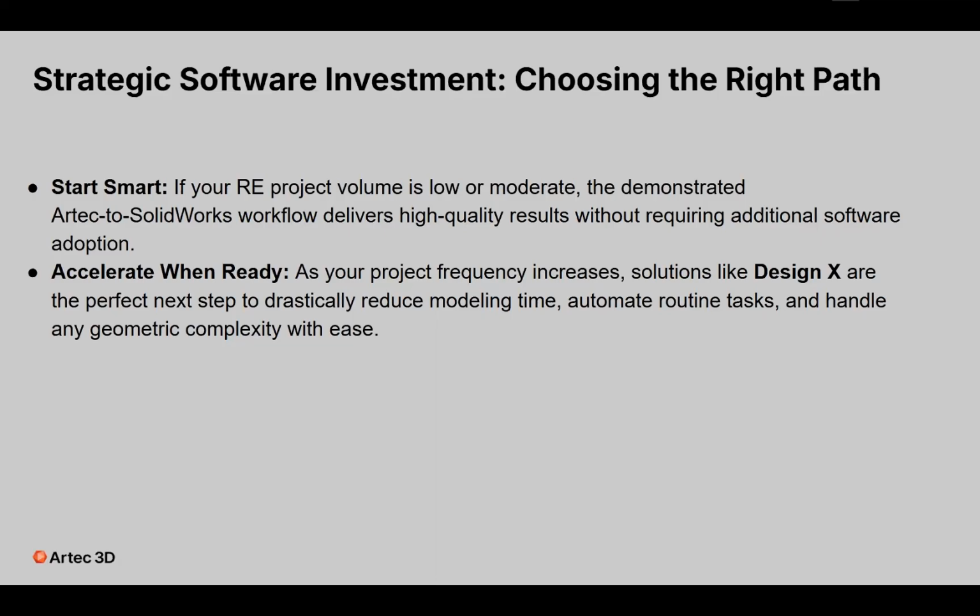But if the budget is limited, if you or your customer are not yet decided whether to invest in a specific software or not, but you already need to use the scanners for your reverse engineering process, then the path that I just explained can be a good starting point, because using the measurements in Artec Studio and using sections and using them in SolidWorks can still deliver a result.